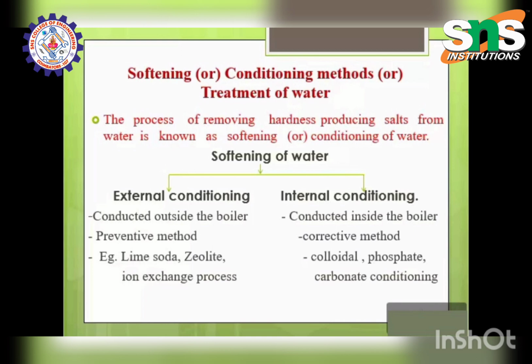In the cation exchanger, the resins contain acid functional groups like COOH, sulfonic acid or carboxylic acid, which are capable of exchanging their H+ ions with other cations of hard water. Cation exchange resin is represented as RH2, a common term. Examples of cation exchangers are sulfonated coals and sulfonated polystyrene.